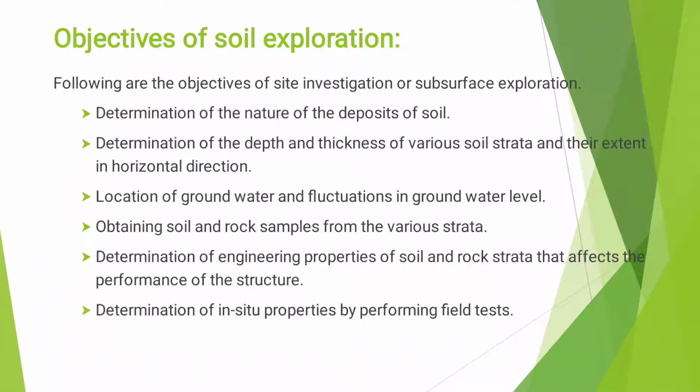So first one is soil exploration. Site investigation is done for obtaining the information on the subsurface strata. Soil exploration consists of determining the profile and nature of the soil deposit at the site by taking soil samples and determining their physical properties by conducting laboratory tests and in situ tests. Next, the objectives of site exploration or site investigation.